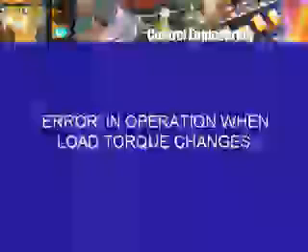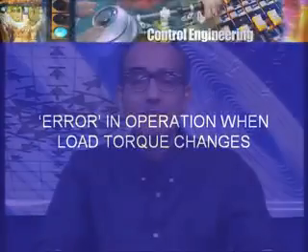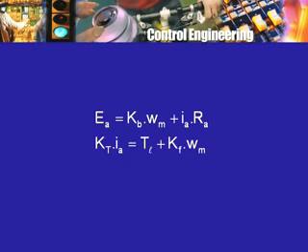So do these calculations yourself. For say 10% increase of load torque, what is the decrease in speed, and typically one thinks in percentages rather than absolute figures. Then you can redo it with 20% increase in load torque, what is the decrease in speed like. So what is the speed regulation of this drive, this very simple crude drive? Most probably this will not be acceptable, but this is a first step towards a better design.